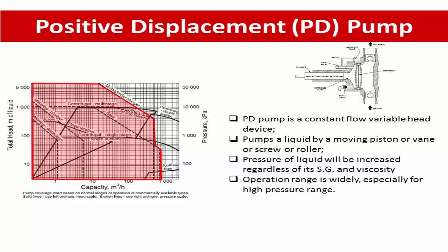Other common characteristics of the positive displacement pump: it is adaptable to high pressure operation. An auxiliary damping system may be used to reduce the magnitude of the pressure pulsation. Variable flow through the pump is also possible, and it is capable of efficient performance at extremely low volume flow rates, with higher overall efficiency than the centrifugal pump because of low internal loss.